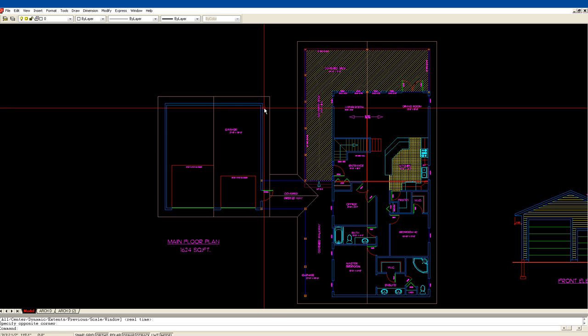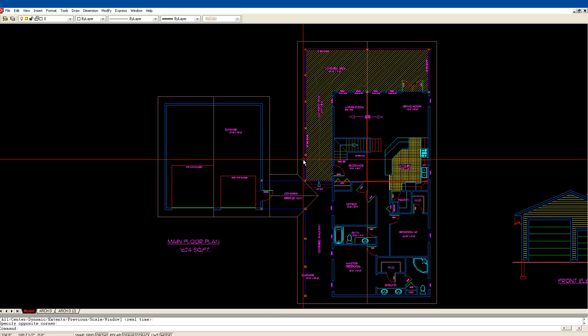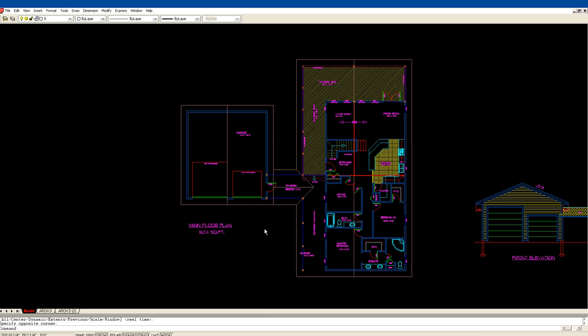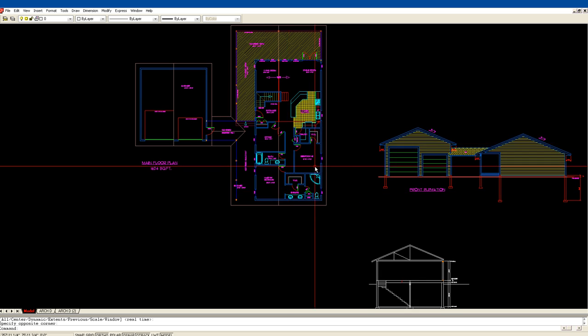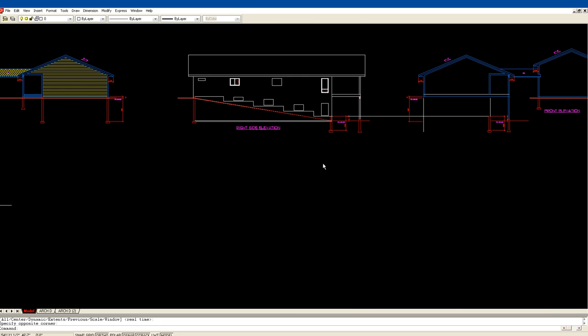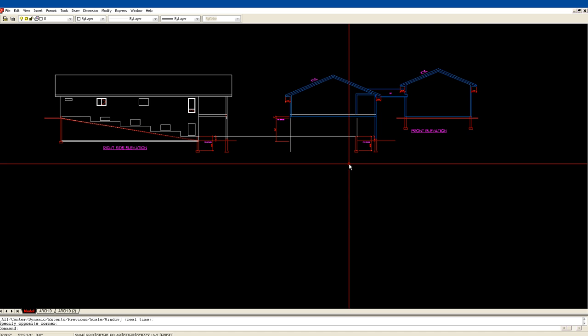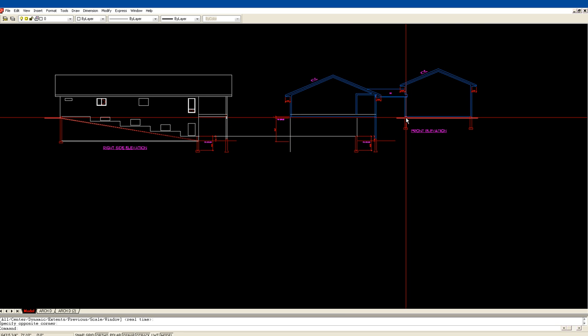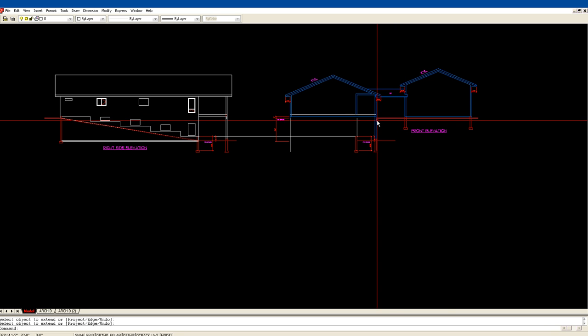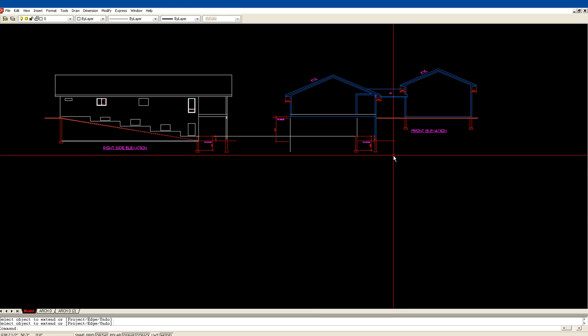So what we were thinking is we will just leave this level inside here, and he will probably move this garage closer to the front of the house. Then from the back of the garage, which would now be about there, he can just grade down and get what he wants. We've already talked about that. He's taken the drawing home and is going to reevaluate it, have another look at his land, maybe take some elevation shots. So basically from the corner of this would be straight across, and then from the back of the garage it would slope down to here.